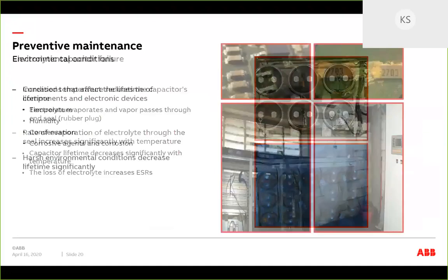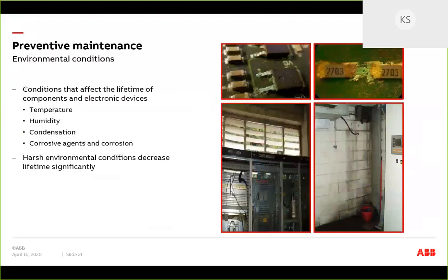This next one is one that blows me away, the corrosiveness of the areas that some of these drive cabinets are put in. Again, Matt, go ahead and share your experience here. Humidity is coupled with corrosive gases or sulfides. Certainly at a paper mill, the mills that make their own pulp, they have even more corrosive chemicals that get airborne, so you can't see them. Sometimes you can certainly smell the SO2, but over time, all our drives are air-cooled.